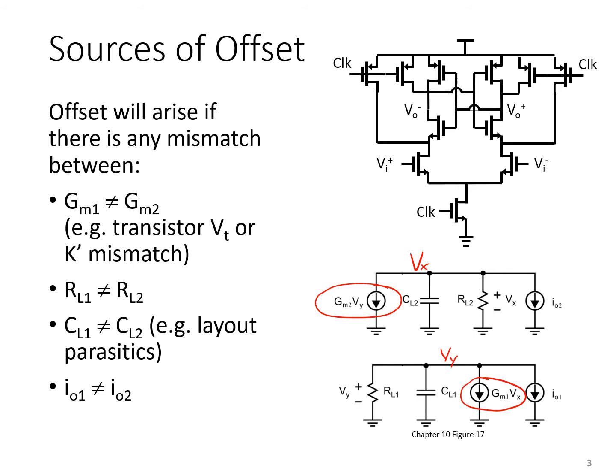So let's say Vx and Vy are both starting up at high voltages, as they would be in the example circuit shown on the top right here. Once the dynamic comparator is activated, both those nodes start getting pulled down low, but one of them gets pulled down low faster, and so it's sort of a race to the bottom. At some point, one will have a head start, an advantage that's insurmountable, because the positive feedback will take over and then regenerate the voltage to something like this.